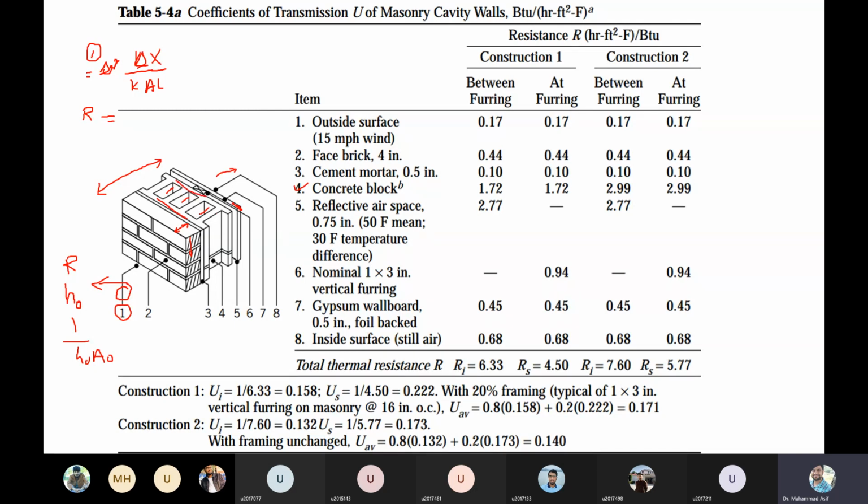The simplest way is, by using the thickness and the nature of the concrete block, you can have the thermal resistance. Then for the other layers, you can adopt the same procedure to calculate the thermal resistance, and then you can add them up because all of the resistances are in series, and you can get the R equivalent, right?